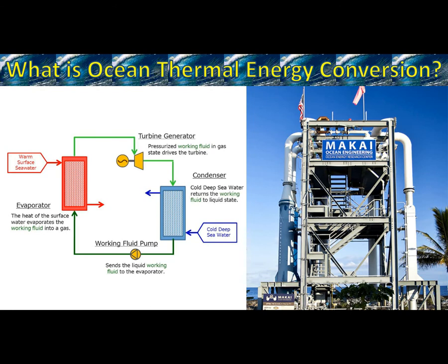This is an example of an ocean thermal energy conversion. In this figure, working fluid is being pumped to the evaporator. Then, the heat of the warm surface seawater evaporates the working fluid into a gas. Pressurized working fluid in gas state drives the turbine to produce power. Then, the cold deep seawater returns the working fluid to liquid state, and the cycle goes on and on.